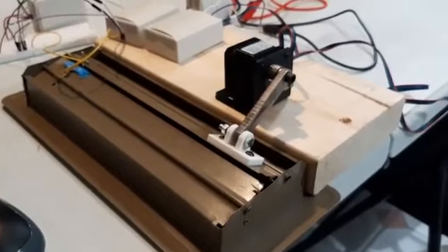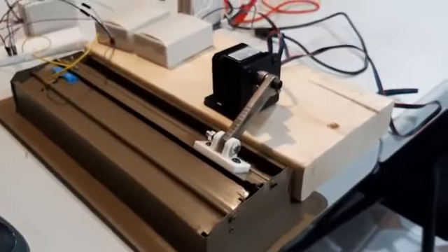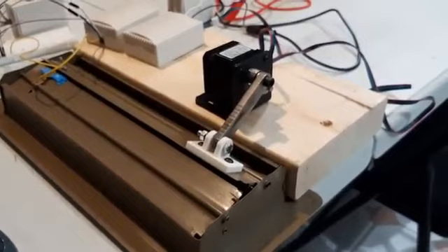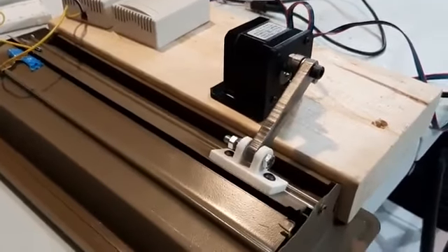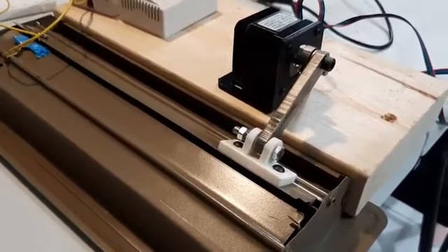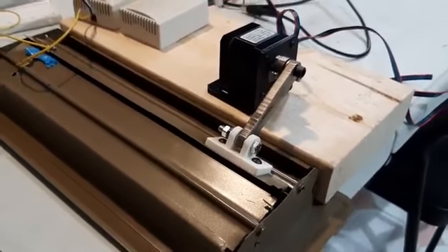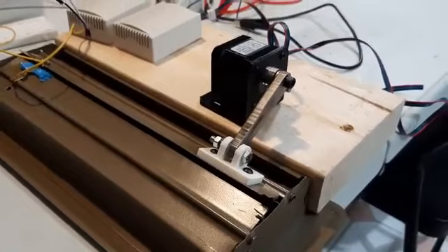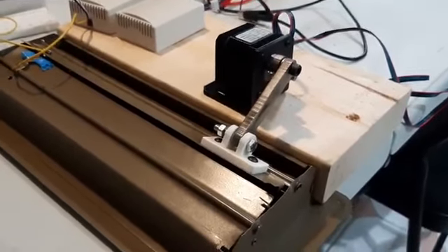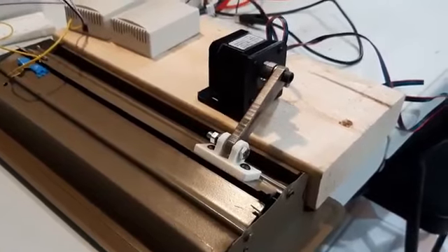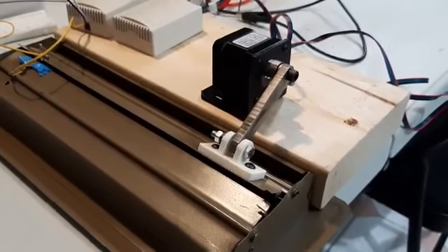Damper opened. But maybe that's not enough because there is no airflow. So now the damper has been opened a little bit, and the percentage will be shown on the monitor, but we are waiting for more opening because the temperature doesn't change, since there is no airflow here. And we are testing it in cold mode, not in hot test mode.